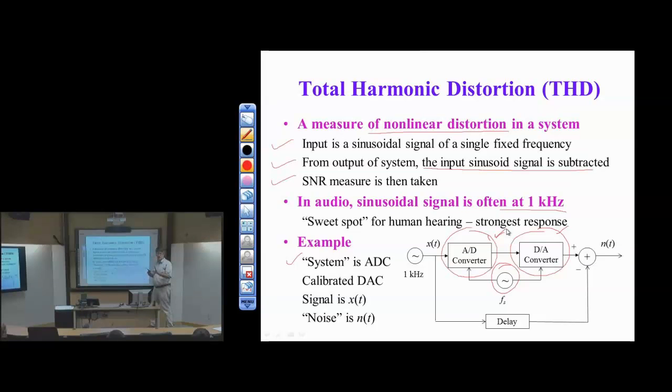So they're synchronized automatically. So I feed in this 1 kilohertz analog continuous time signal. I go through A to D conversion, go back through D to A, and I assume that I've already got a good calibrated D to A. And we already know from the previous slide that D to A has more accuracy than A to D in general. If you have multiple converters like that, where you have A to D and D to A, and each of them has their own SNR,